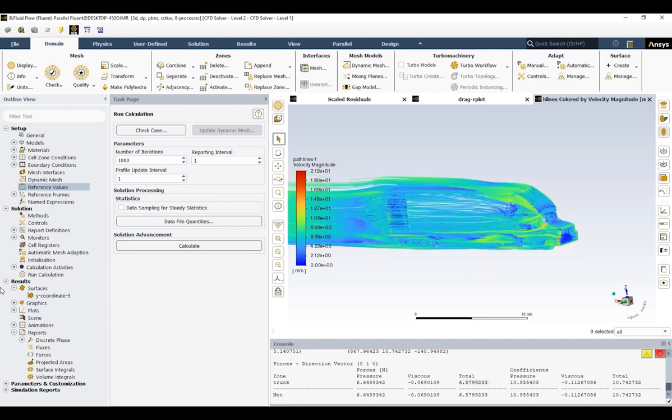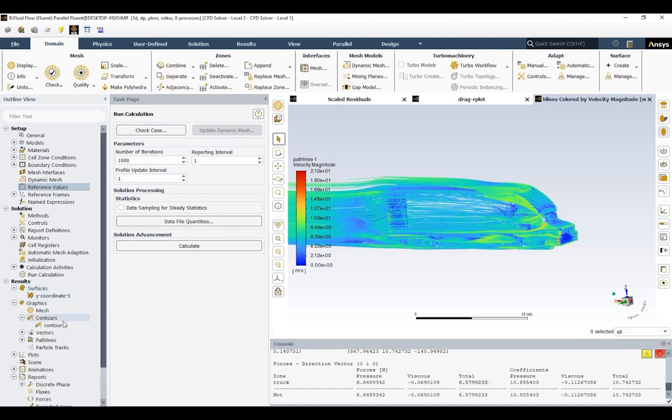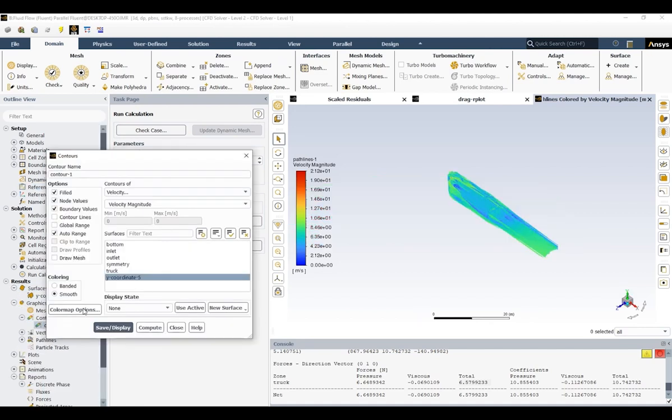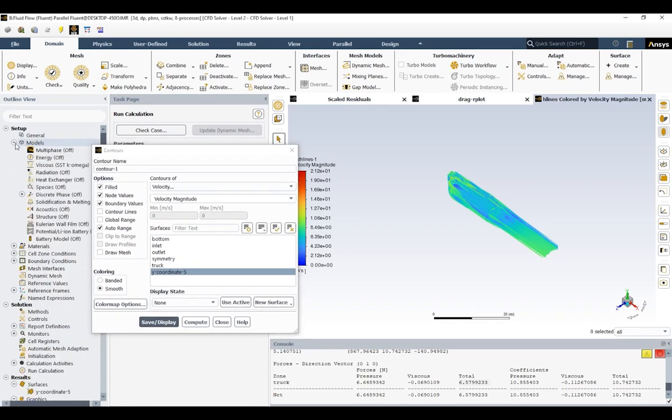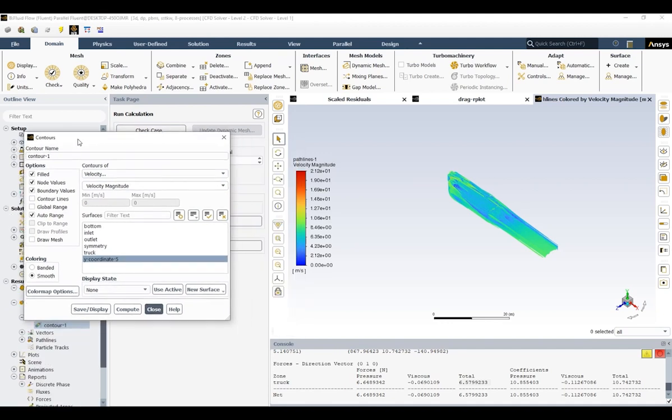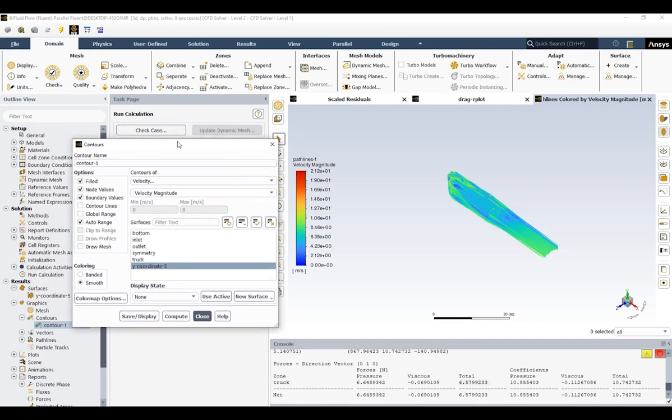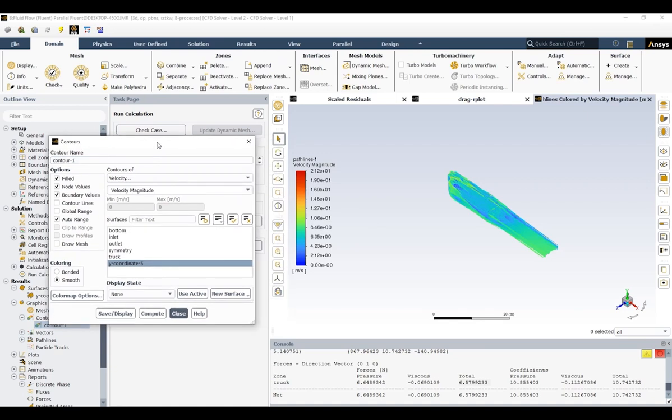But before actually finishing the tutorial, I'm gonna have to show you something else. As you all can probably remember, we talked about y plus value when we were talking about the SST k-omega model that we have used in this project. As you remember, I mentioned that when we are using this SST k-omega model, we need to make sure that the y plus value over the surface of the truck is actually less than 1, is between 0 and 1.